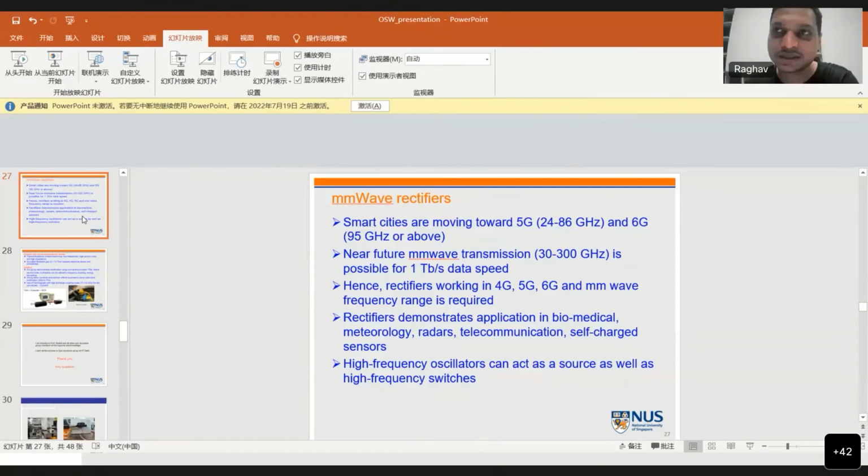Okay. And of course, this canted angle is very important. When we have a certain canted angle, something like 45 degrees, you require very low power to excite this. And what was the TMR in these devices? Typically 70 to 80%. Does it matter? Yeah, it matters. Of course, the voltage is directly proportional to TMR.